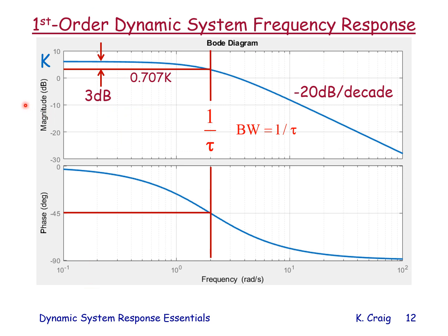Let's look at the first order dynamic system frequency response. Frequency response means if we input a sine wave into the system and we wait till all the transients die away, the output will be a sine wave, same frequency. It has to be. The amplitude will be different, and there'll be a phase shift. Both the amplitude and the phase angle depend on the frequency of the sine wave that we use.